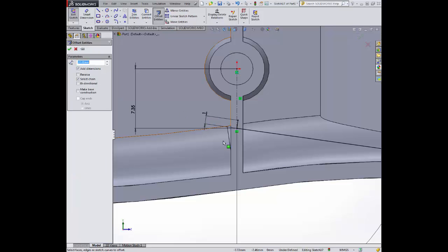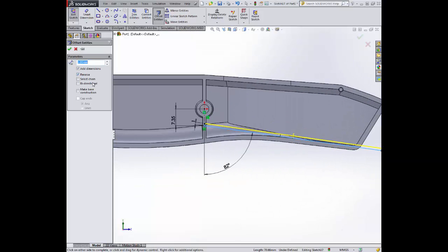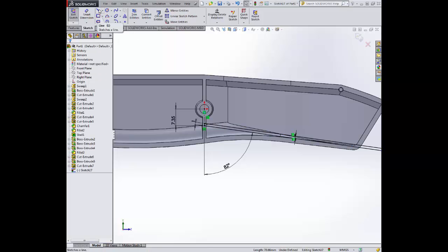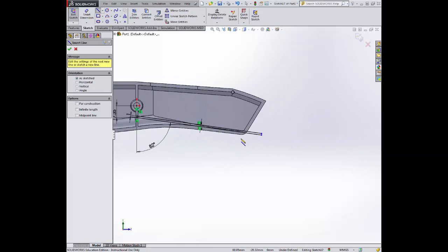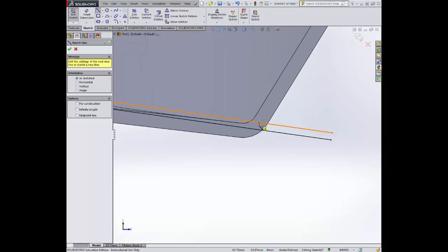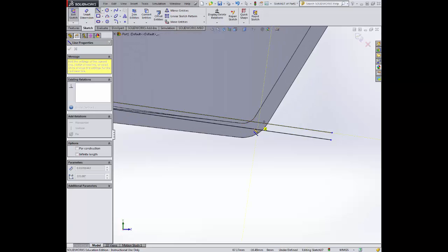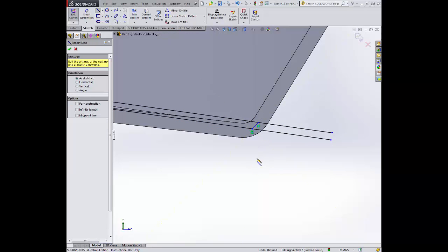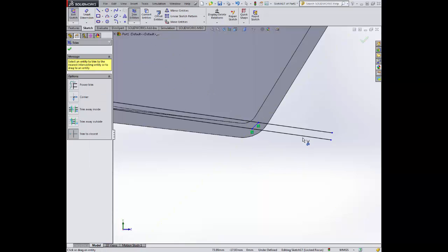Different way of doing a line that's parallel. Click on this one. Now it's selecting chain, so I'm going to deselect that and go for 1mm. Reverse the side so it goes the other way. That's what we want. Okay, and then within the boundary, because we want the 2 to merge as a face, click on there and I'm going to trim off these end pieces.